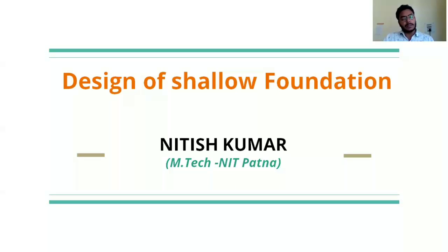By keeping some factor of safety, whatever the contact pressure that comes at the base of the footing should always be less than the bearing capacity of soil. Otherwise, it would fail. And that bearing capacity of soil we have already calculated in the previous lecture. We have seen the various methods to calculate the bearing capacity of soil.